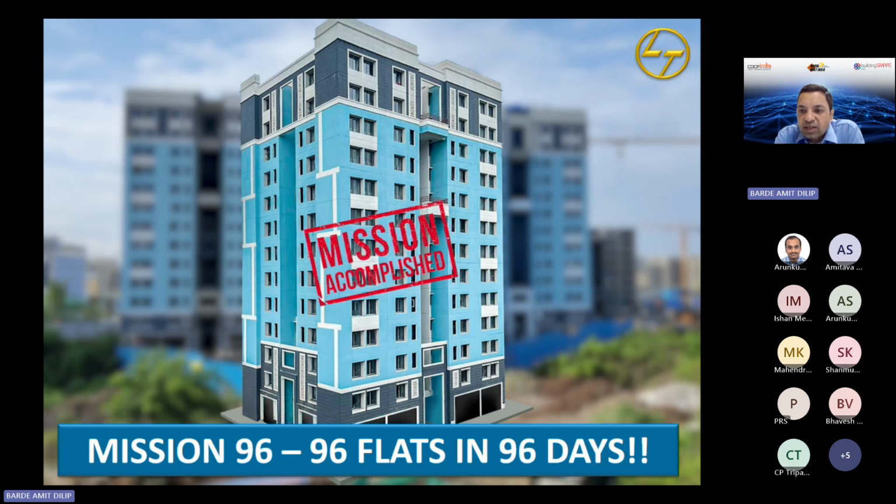But if you see the structure itself, what was built in precast technology was completed in just 36 days, right? So a cycle time, what we call it, is the time required for each floor. It's traditionally about 15 days or so on paper. Comparatively, in our precast projects we are operating at about 8 to 9 days. And this we wanted to showcase, saying if I add resources, if I give my best, how fast I can build is about 3 days per floor.